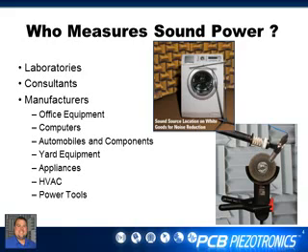And actually, many manufacturers around the world perform sound power measurements on office equipment, computers, which you would think computers, well, they're pretty quiet already, but once you have a large group of computers, that becomes additive. It's just like everything else. It's superposition of sound. And as you increase the number of sources, the overall sound power level increases as the sum of the sources. Automobiles and components, yard equipment, so lawnmowers, tractors, weed whackers, they're all on the list of things that are tested for sound power.